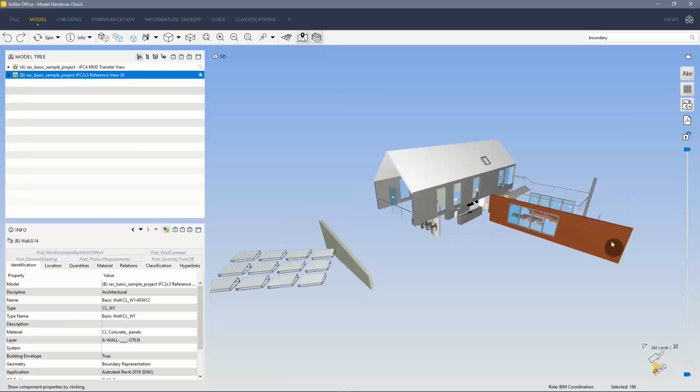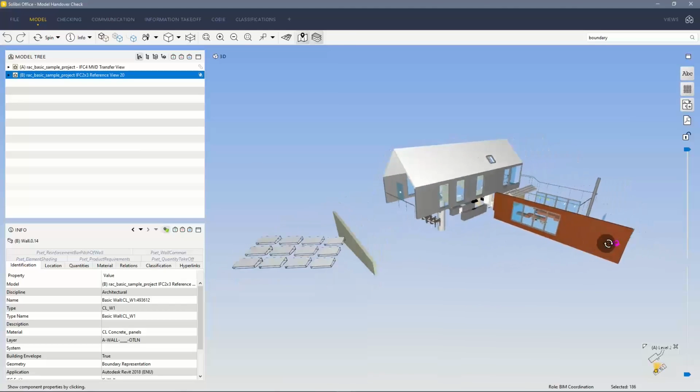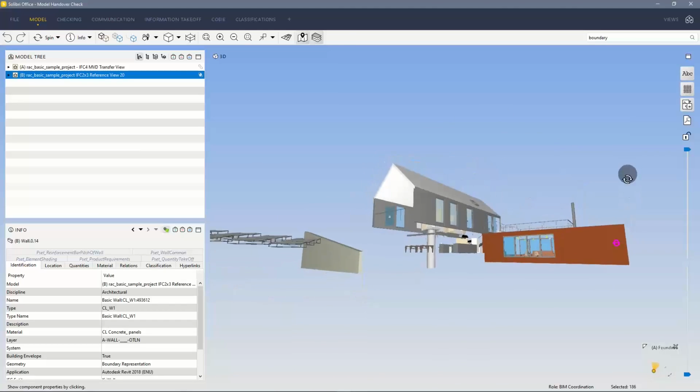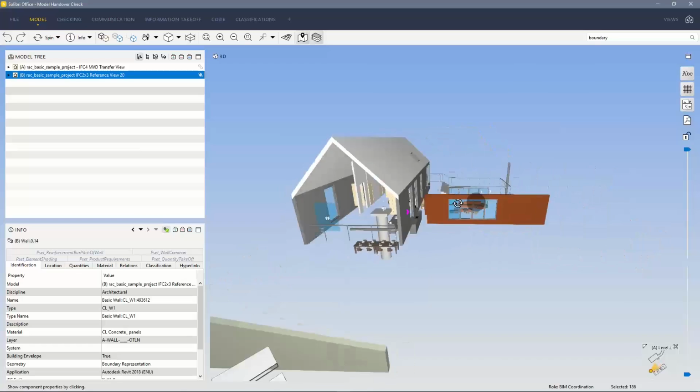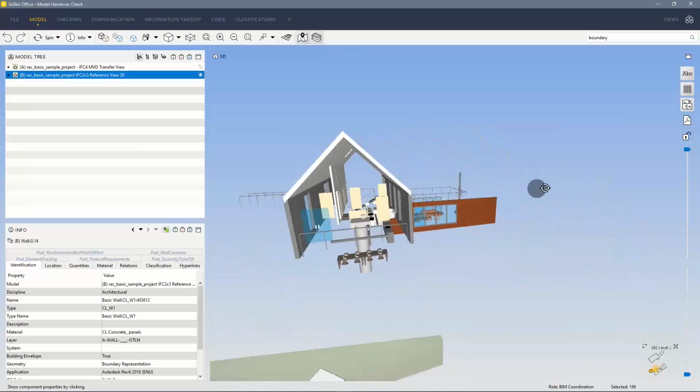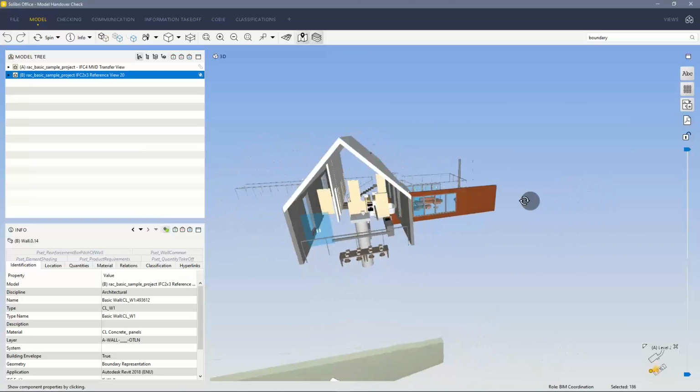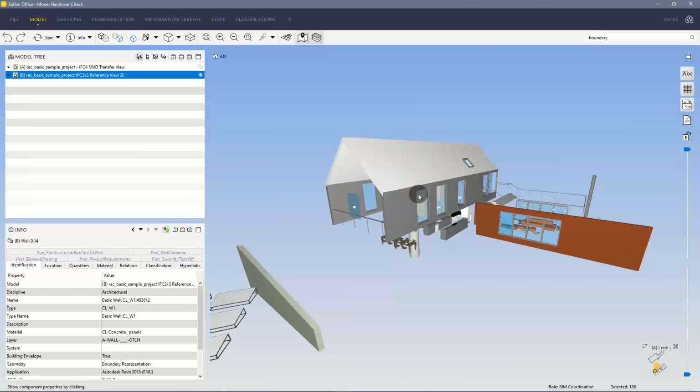If Archicad cannot build this element as a wall, well, there's no way for Archicad to do it, since the original geometry is not an implicit geometry. So when you have those types of errors, it is always good to go back and double check the IFC, to check whether Archicad is doing something wrong or if it's just the translation from Revit to IFC.